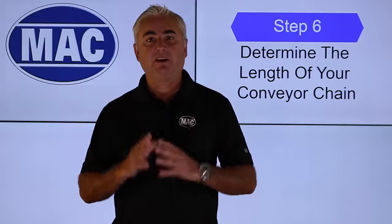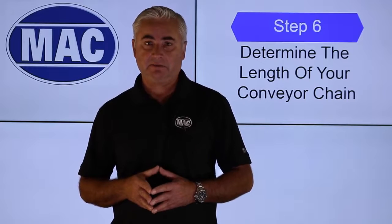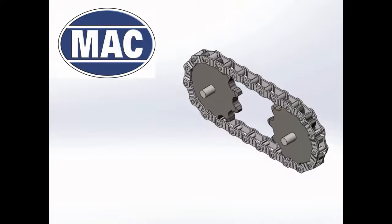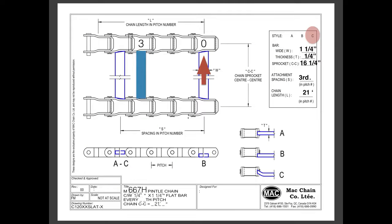Step number 6, the final step of this process, measure the length of your conveyor chain. To measure the length of your conveyor chain, measure center of the drive shaft to center of the idler shaft, times 2, and then calculate from your predetermined chain link size enough links to cover the top and the bottom of both sprockets.